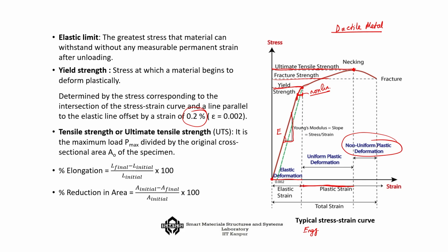So, beyond which the plasticity happens, that is a sort of thumb rule. So, you can see the 0.002 value here plays a very important role, that 0.2%. Now, of course, for rubber or such polymeric systems, elastomers, this can go up to 10%. Okay. But these are different types of systems, that is why I said that this is mostly for the ductile metals.